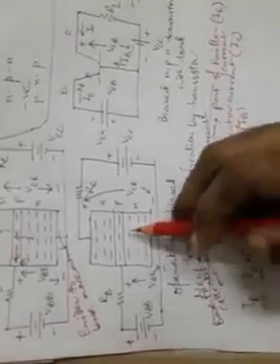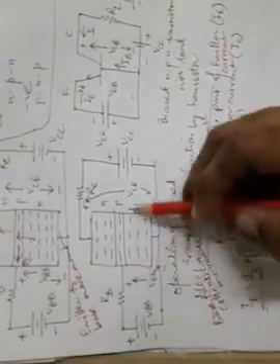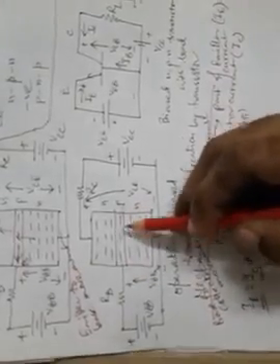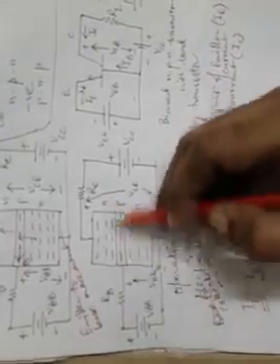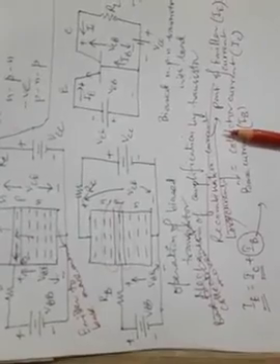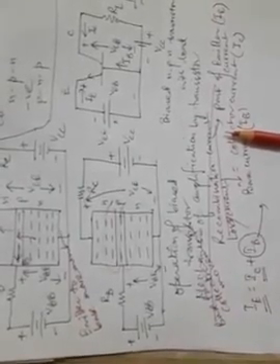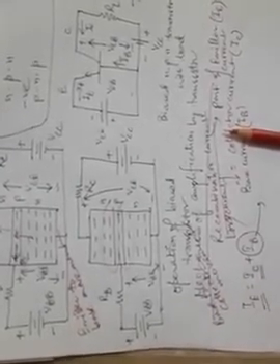For a reverse bias junction, the dynamic resistance is large, so we can say that the junction resistance around the emitter base area is small and the junction resistance at the collector base area is large. So the two junction areas have two different resistances. So the transistor action is happening, actually a current is passing from a low resistance input circuit to a high resistance output circuit, resulting in power gain.